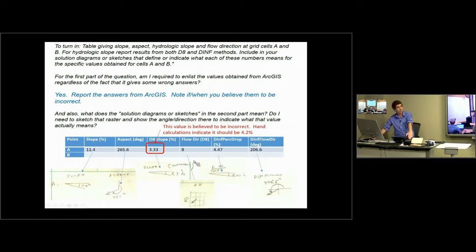So this is the vertical component of the slope, as Dr. Maidment just mentioned in the point he made previously, whereas aspect is now an angle, aspect being measured from north, so we've got north, and it's coming around to, in this case, 265, so it's almost all the way around to 270 degrees. So you can depict that the aspect is that direction from north.